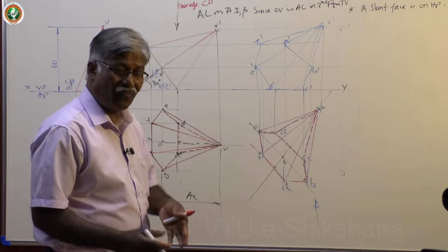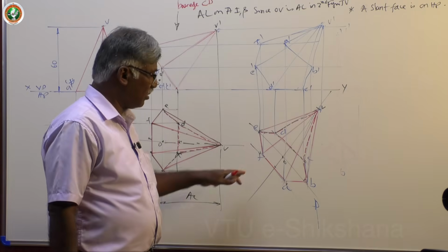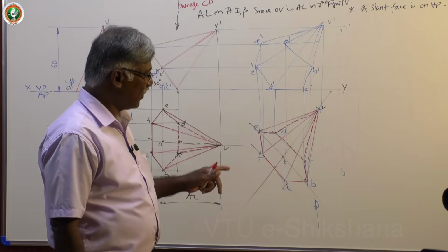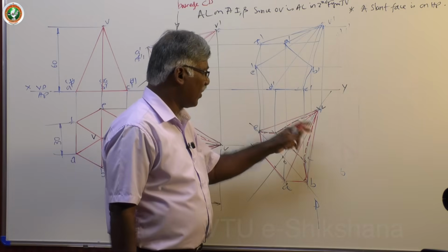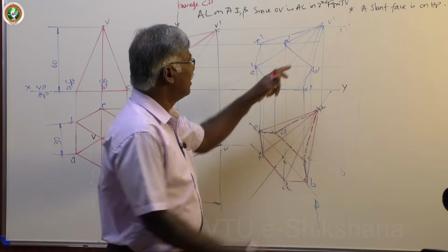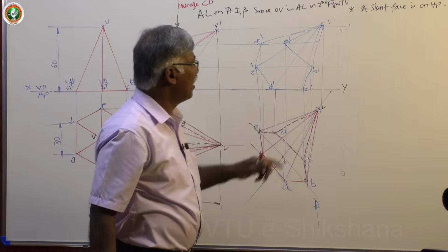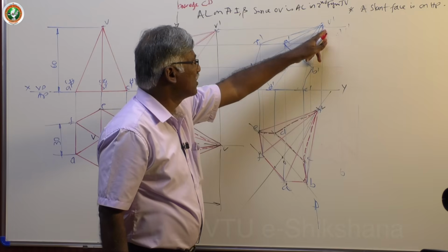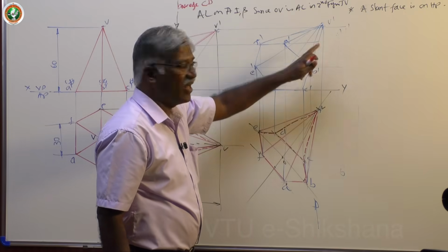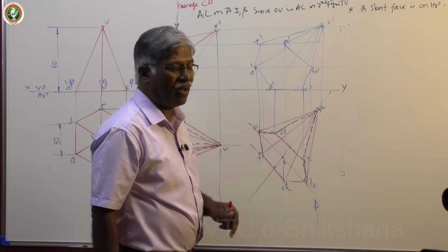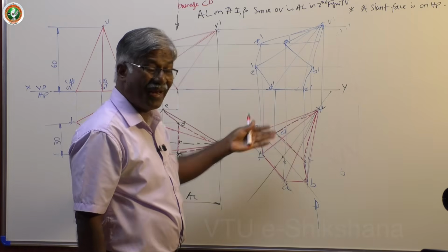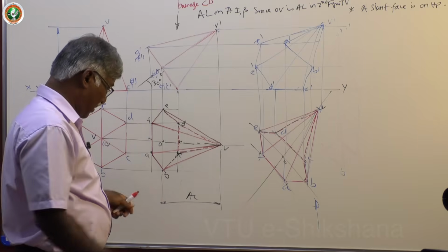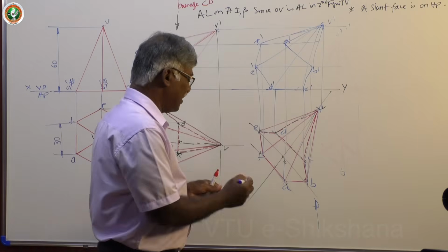Whether we go for the farthest point method or the key surface method, I prefer the key surface method, because the farthest point is V. Fine, V is not visible. All lines joining the point V are not visible. There are boundary lines, fine, I can accept those to be dark. But what about the other lines? There will be confusion whether to draw a dark line or dotted line. But the key surface method is very easy.